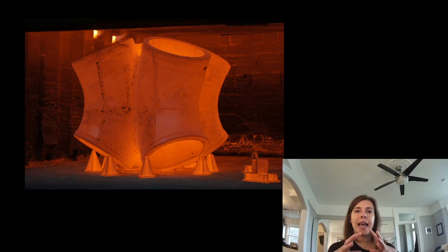Because when it's in the sand cast, they control how it cools, but if it cools too fast, it would crack. So they can do that to like 95% accuracy in the sand cast mold, but sometimes what they'll do is heat temper it again, where they'll heat it back up and allow it to cool in a very controlled way.